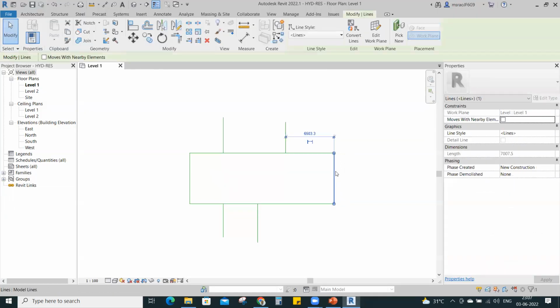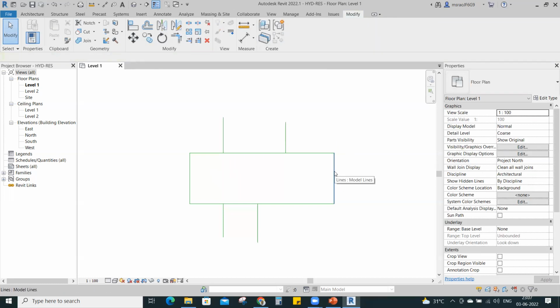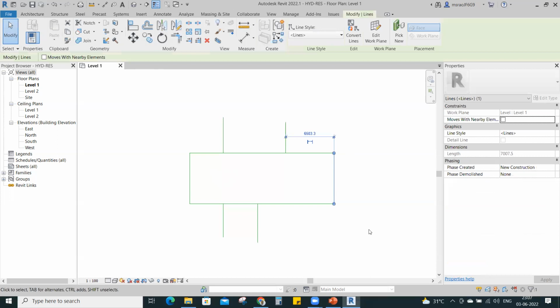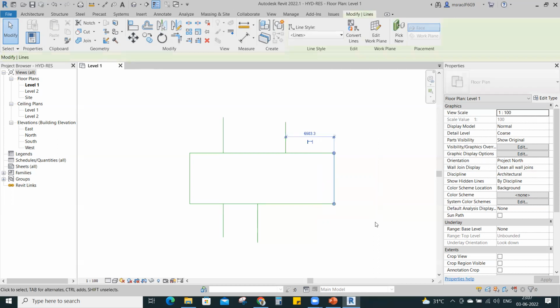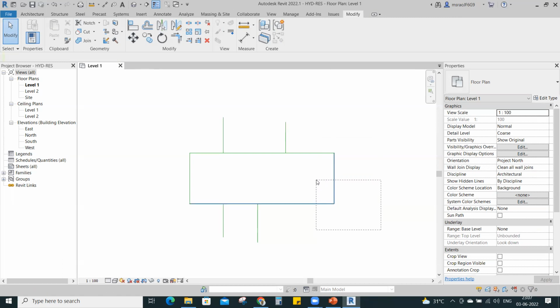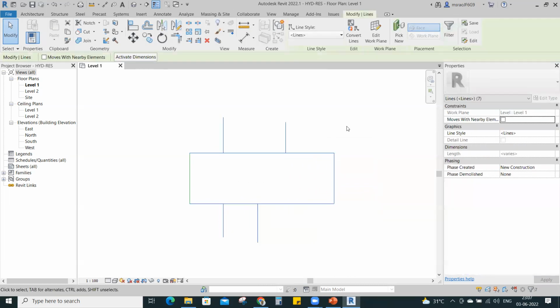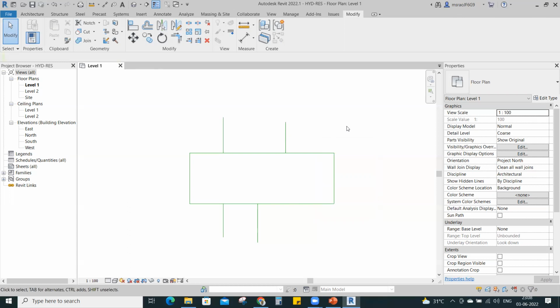Before moving, you have to select the object. If you click on the object, it is the object method. If you click on top left, coming to the bottom right, okay, if you see a continuous box, we are calling it a window. If you want to select an object, the object should be enclosed by this box. And the cross, I'm clicking the first point from the bottom right and going back to the top left. Whatever touching this box will get selected. This is the cross method. Object method, cross method, window method.